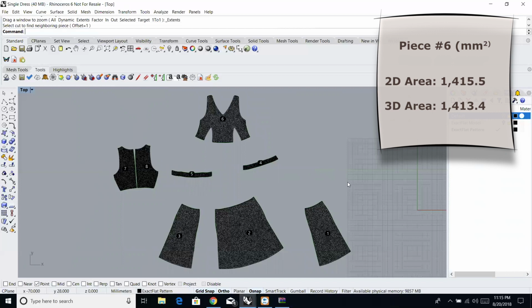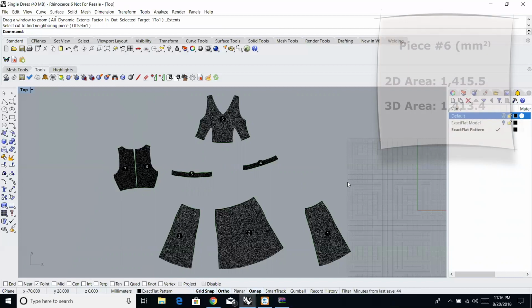So now we've got our flat pattern pieces and we've got our graphics on them. Yeah. I suppose we'll leave for another day the actual manufacturing and showing how this dress fits. Sure, absolutely. So once we get to this point, to export it out to the Reggiani printer, we have 2 ways that we can get the file out. We can either create a PDF that has the raster and the vector information, so the cut and the print information, or we can create a TIFF and a DXF file, or a variety of other graphic files, depending on how your system works or what you're looking to do.